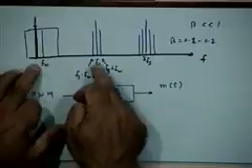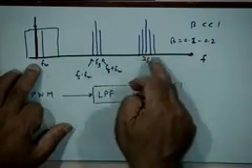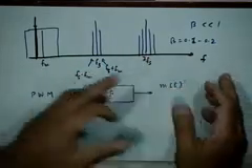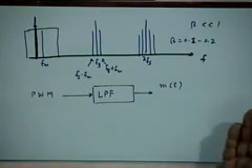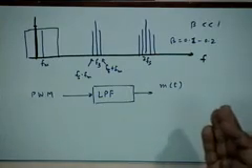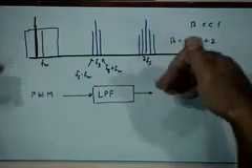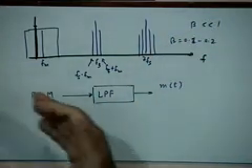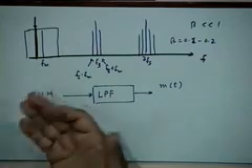Of course, your concern is slightly different. Your concern is that you have this repeated spectrum because of the sampling itself, and it blocks the whole frequency axis. But the very fact that you agree to use pulses implies that you have sufficient bandwidth to transmit the spectrum, because that is implicit in time division multiplexing, and you can't do much about that. So basically, our data rate of interest, our information rate, is much smaller than the bandwidth available to us. It's only that it's convenient to work with time division multiplexing in this case rather than frequency division multiplexing.